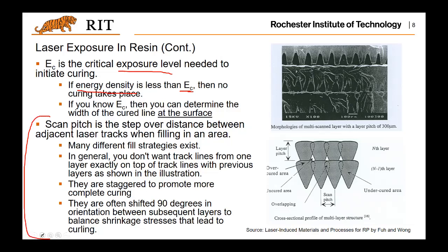Another point is the scan pitch. As we mentioned in the last lecture, there are two scanning pitches. One is the layer pitch, and the other is the scan pitch. The layer pitch represents the overlap of the cured region among layers, and the scan pitch describes the overlap within the same layer, among different scanned paths.